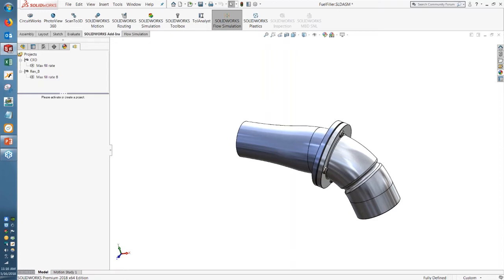So for example, in this case, if I wanted to, I could simulate not only the hydrogen flowing inside this nozzle, but the air around the outside, or even simulate the hydrogen flowing out the end of the nozzle to see what would happen if it were just going into a big empty tank. For right now, I'm really just concerned about the effect of those internal bend radii and other factors. So I'm going to do an internal analysis here to focus in on that, and that'll make sure it runs in a more reasonable amount of time.